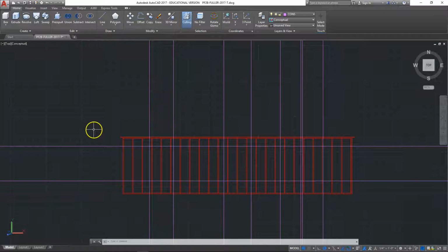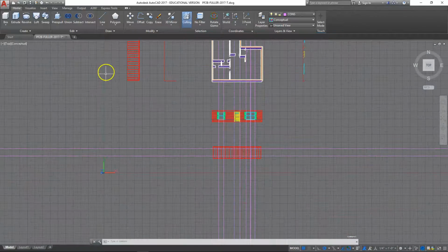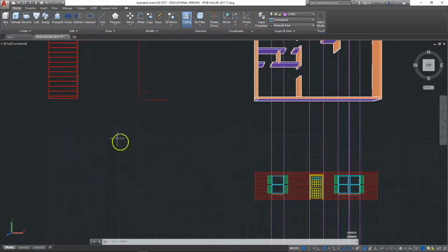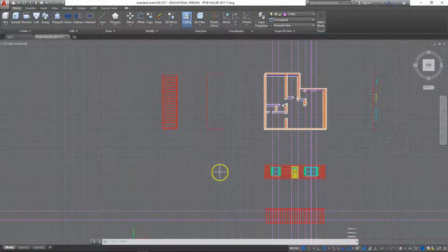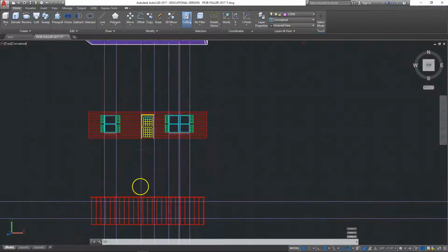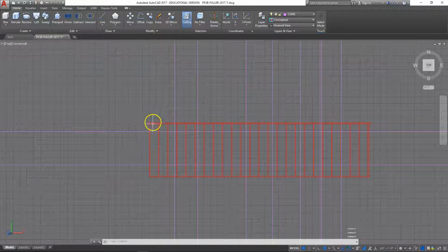The top plate on the west wall was cut 3.5 inches shorter at each end to account for an overlap of the wall it is tying into. The front wall has a 3.5 inch extended top plate at each end to fit into the slot created on the west wall. The same technique will be used on the east wall.